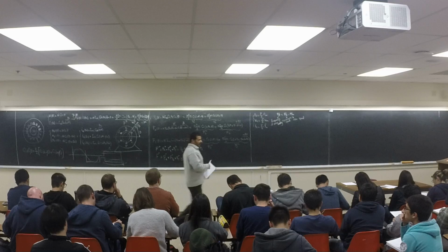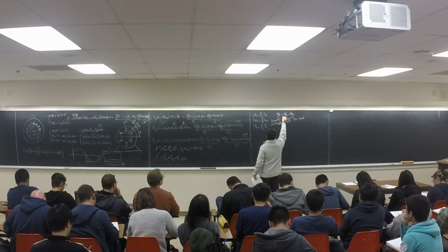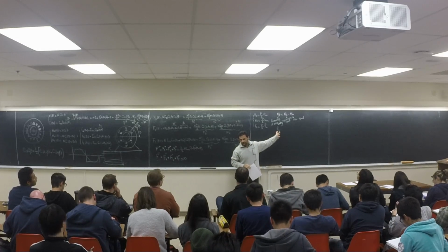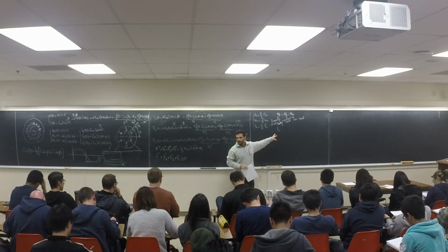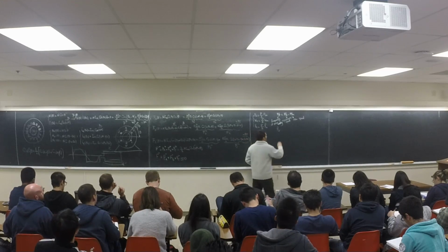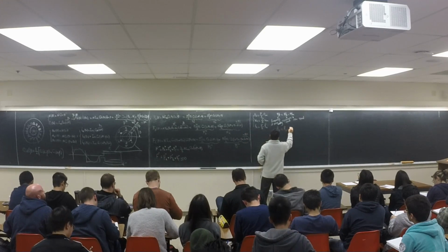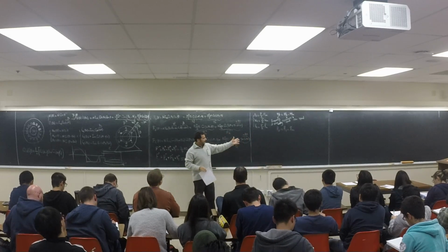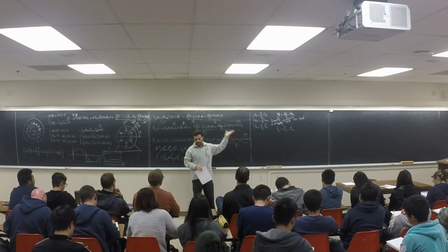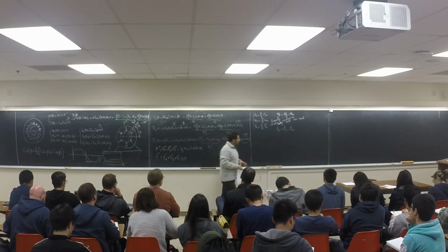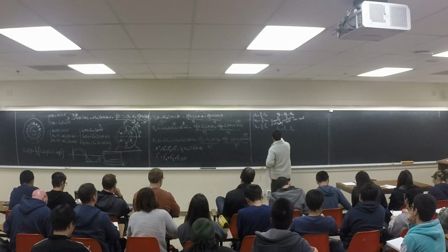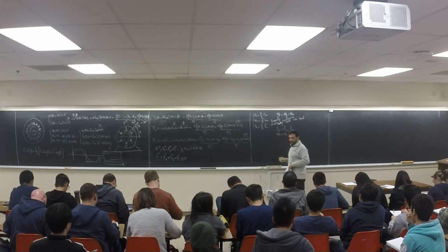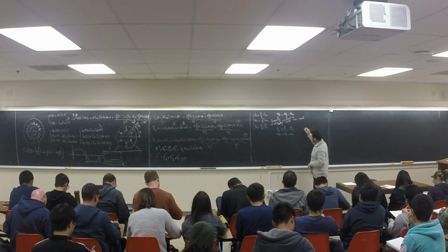Now, basically I can write it this way. I can say Fr, now this is really frequency. Frequency of the rotor winding. We have a current in the rotor winding. Frequency of that current is going to be Fs minus Fm. And how to calculate Fs and Fr, Fm and Fs? Let me go over that one first. Or you can say omega r, again another thing, is equal to omega s minus omega m. You can put it any type of equation you want.